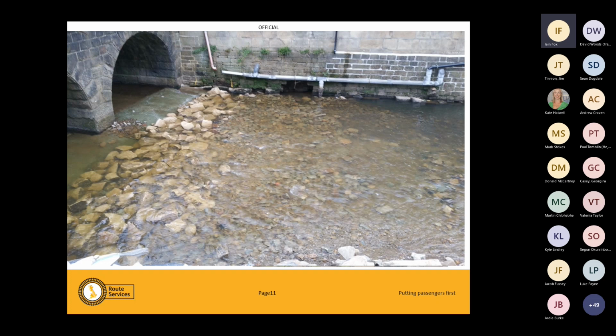If we break that, we're in a world of pain. What we should have is a transition material. So you've got hard concrete invert coming through the structure. You've then got some rock armour placed downstream before it goes back into the natural bed.